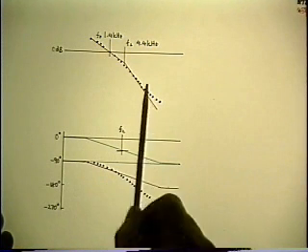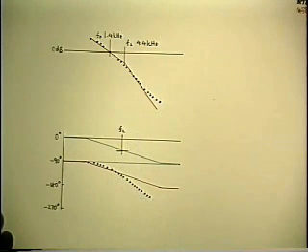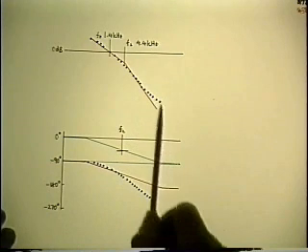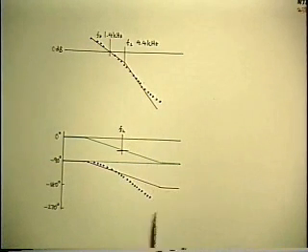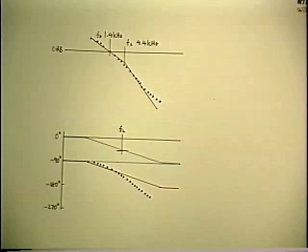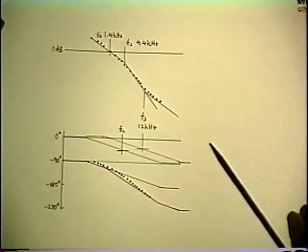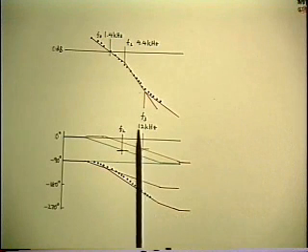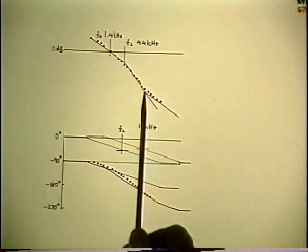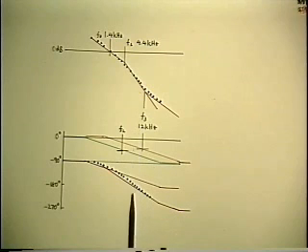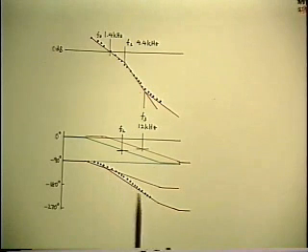And this suggests you'd better pay a little more attention as to why that 0 is there, because it's that old nemesis, a right half plane 0, that has a lag instead of a lead. And when you do the eyeball least squares fit business with your straight lines to determine where the corner is, it's 12 kilohertz. And you get a consistent corner frequency from the phase, except that it's a lag instead of a lead.